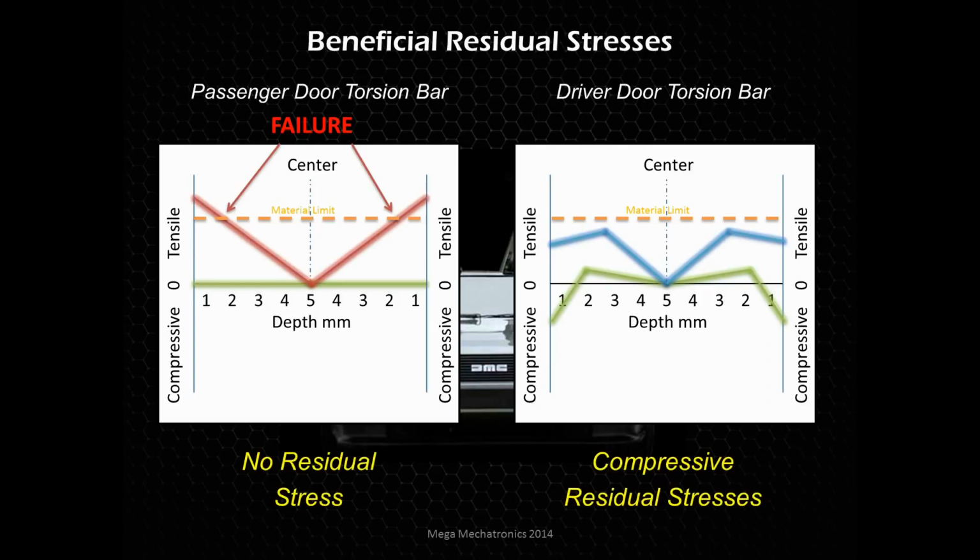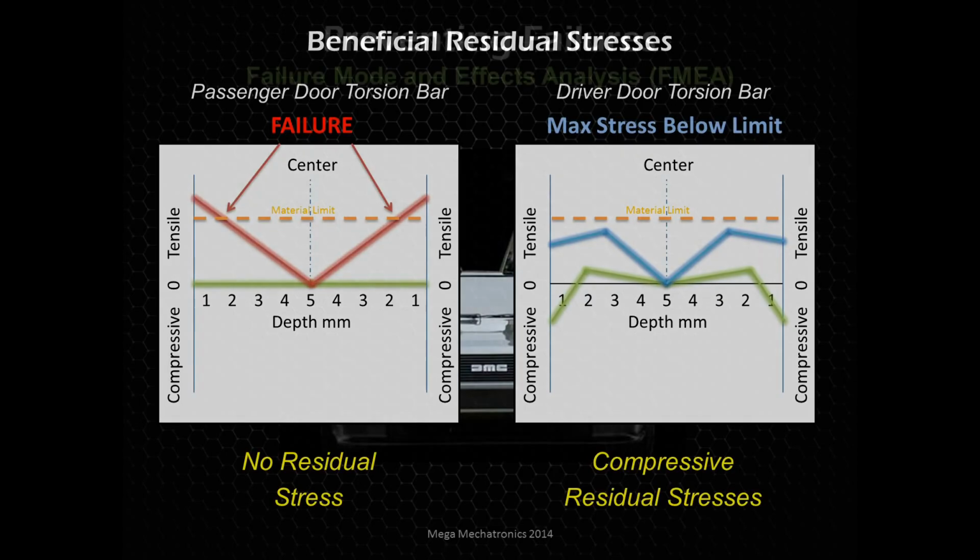So this concept here is what makes valve springs so durable, and makes them last so long. Crankshafts and any parts that are cyclically loaded. Aircraft, this is a very big deal. These compressive residual stresses within airplane parts, very important. So again, the max stress is below the limit.